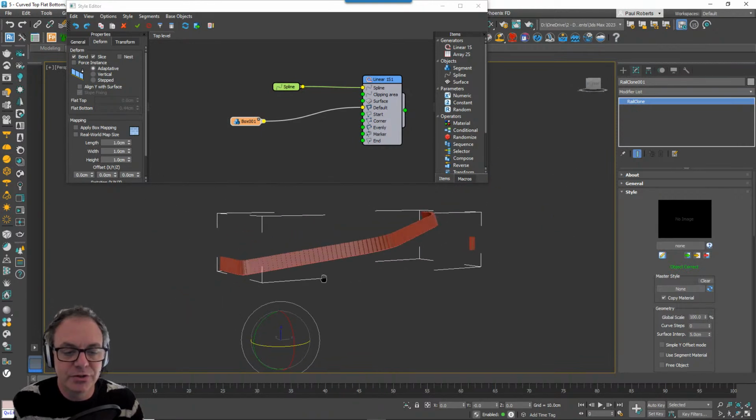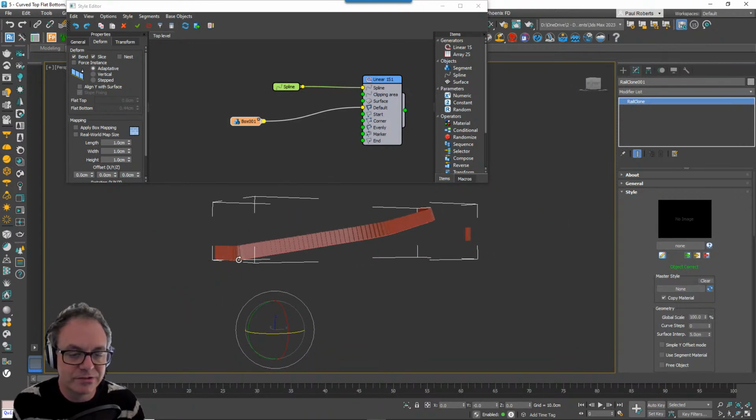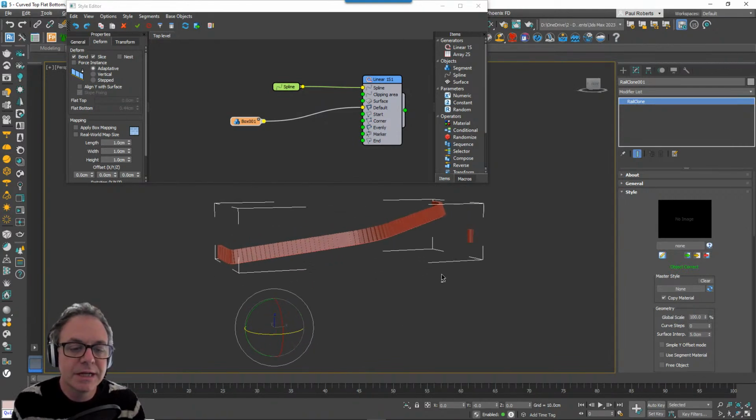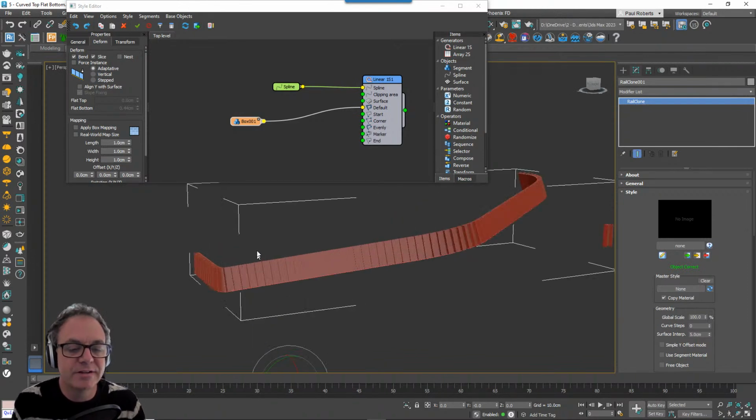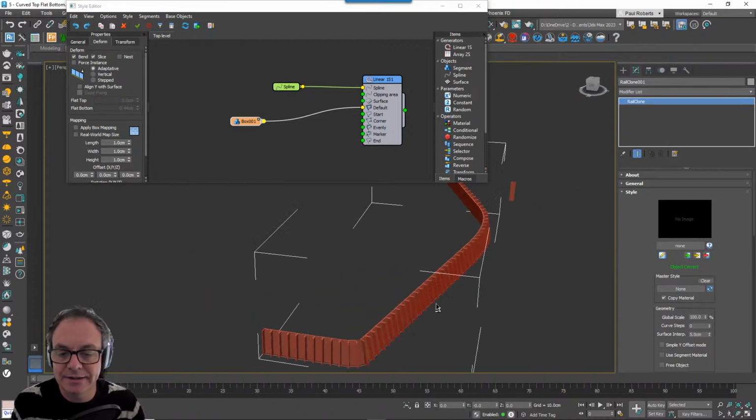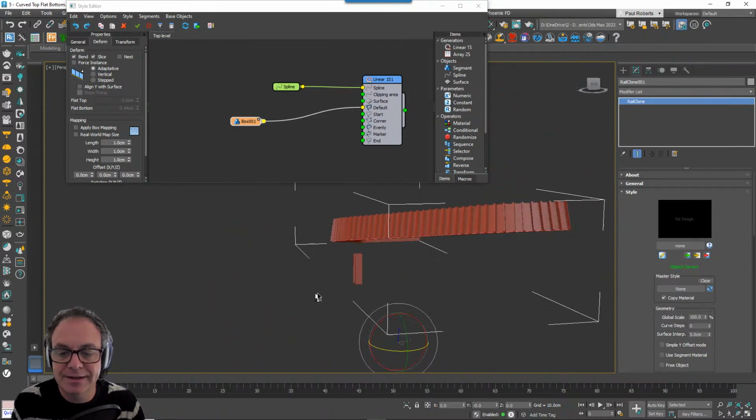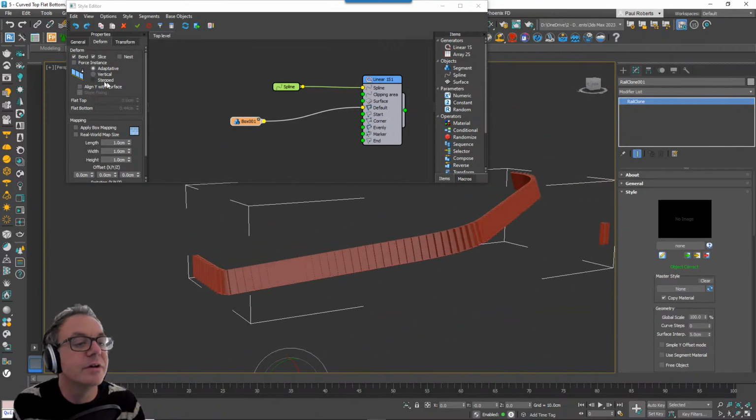What we want to do, or what the user wanted to do in this case, was to have this coming flat along the bottom so that it came up and matched this line up here, which was the top of the roof here. And so the first thing that we wanted to do was to change this so that it was vertical or stepped. Let's go for stepped in this case, so that it's no longer leaning in. You can see it's kind of leaning in to follow that spline at the moment, and we don't want that.